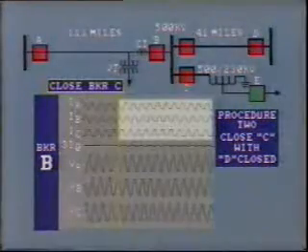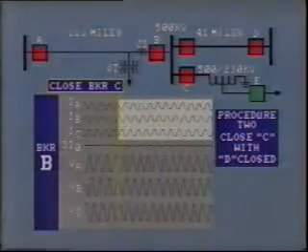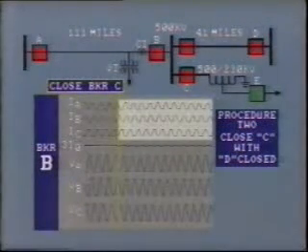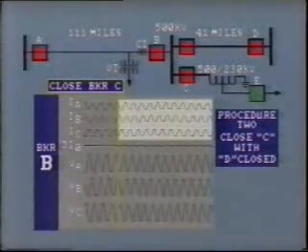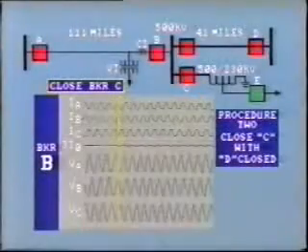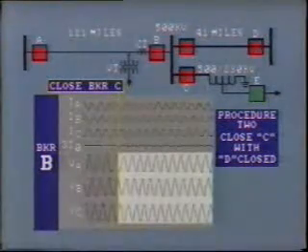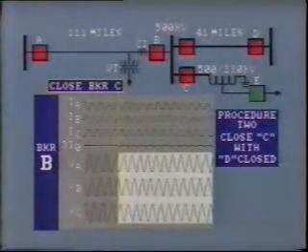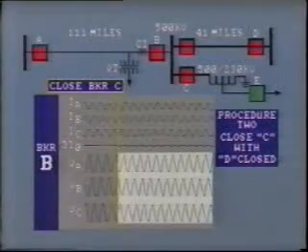In fact, you cannot even see the magnetizing current on the oscillogram because it is very small and superimposed on the normal load current. But you can see that the transformer voltage is now much less distorted, so the insulation is less stressed. Our lesson here is quite simple.